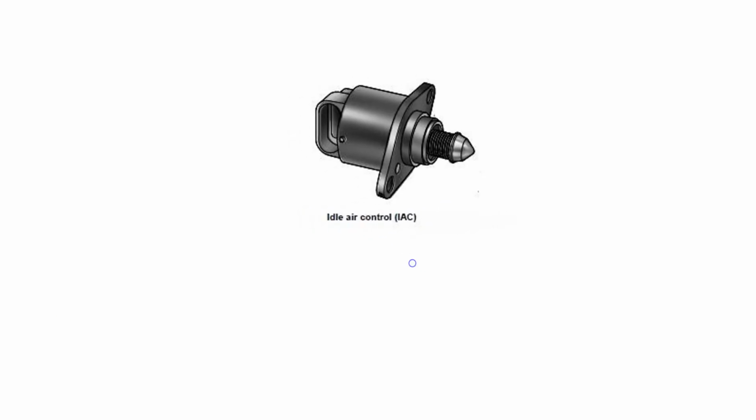The last actuator that we're going to look at is called the idle air control. An idle air control valve is pretty basic. On the inside they have something called a stepper motor. That motor activates, it's got a bunch of little coils, and it makes this little button here push in and then come back. It's able to move it a short distance and a long distance and stop it whenever it wants. It's not a simple on and off.